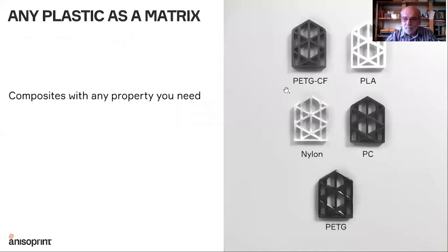Of course, strength and stiffness are the properties that are defined by the fiber reinforcement, but there are other properties, mostly surface or volumetric properties, such as temperature resistance, chemical resistance, resistance to wear, fatigue or impact resistance, or flame retardancy.